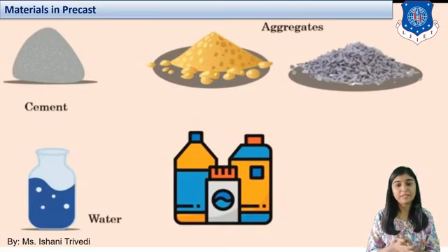The voids between the coarse aggregate will be filled by the fine aggregates. Water is for lubrication and workability, and this makes your full wet mix of concrete. And the admixtures are the chemicals or minerals added specifically for altering, modifying or improving strength or any other property of the concrete mix.